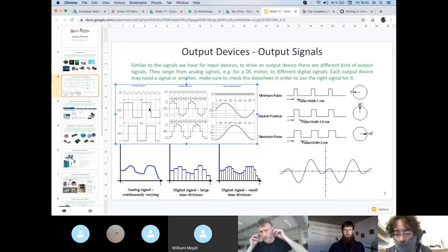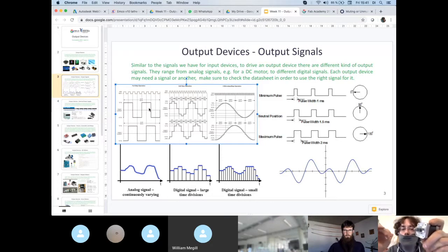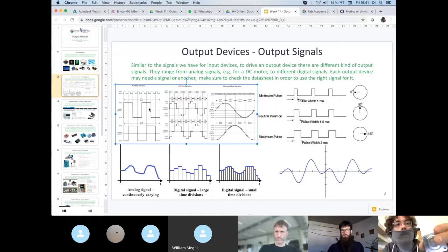With some advancement in the electronics, what we are nowadays able to do is to divide the hardware step declared by the manufacturer of the stepper motor into sub-steps. This means that we can achieve higher resolution, or more steps per revolution. These are called micro-stepping operations for stepper motors, and today they can reach up to 1/256 steps.